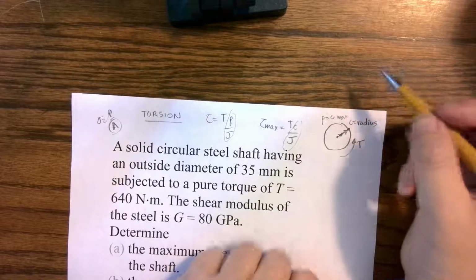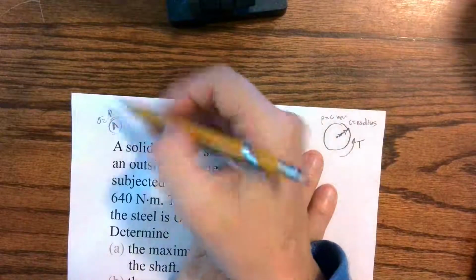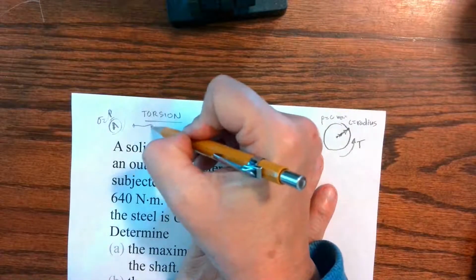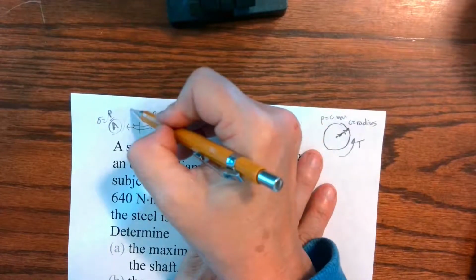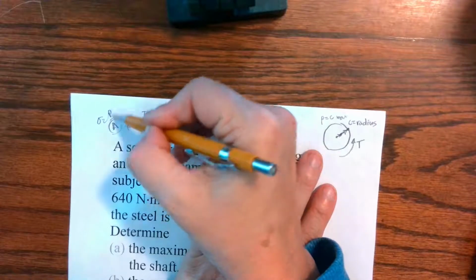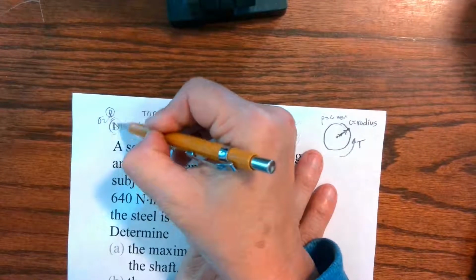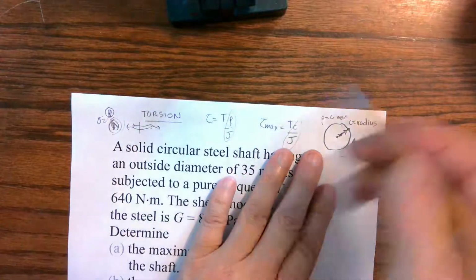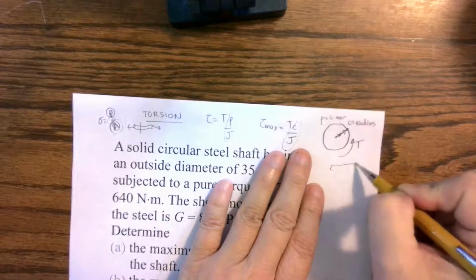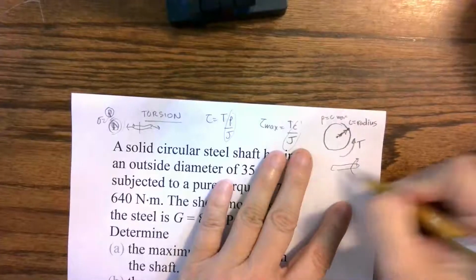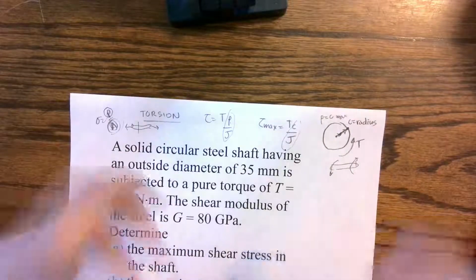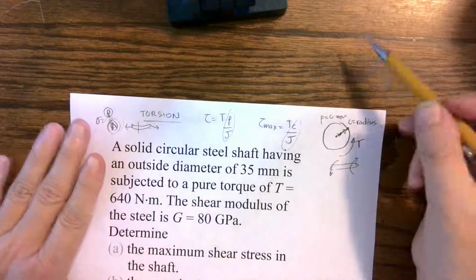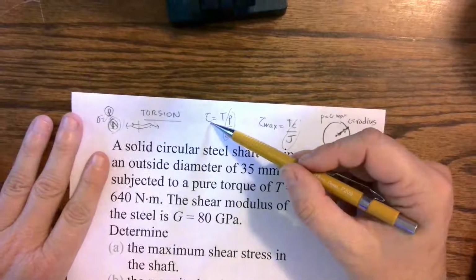So we've had P over A, where we have longitudinal, and we're pulling straight through the axis, and we can look at a cross section, and it is the internal resisting force P divided by the area that gives us our stress. Now we are looking at the same system, but we're going to be twisting it. We're now twisting it like a wash rag. Twist, twist, twist. And it develops shear stress.